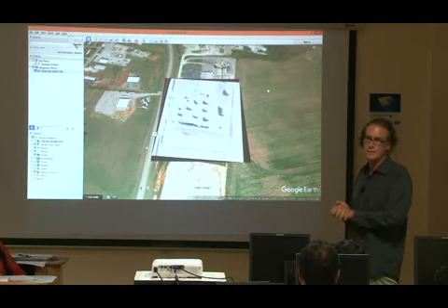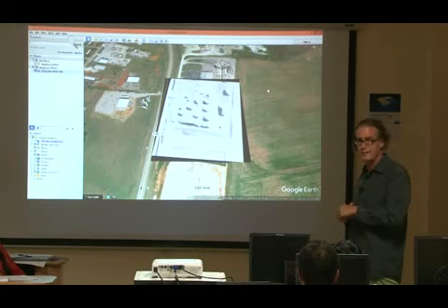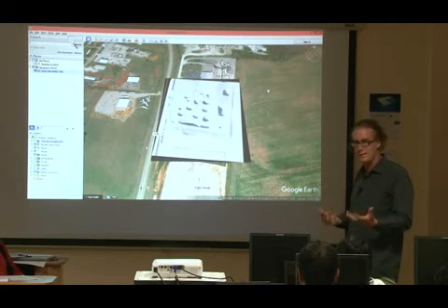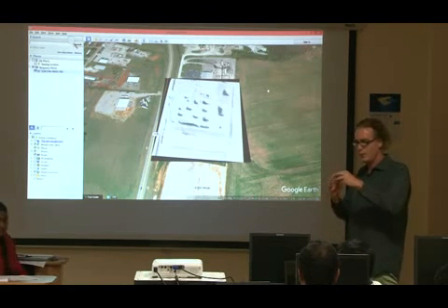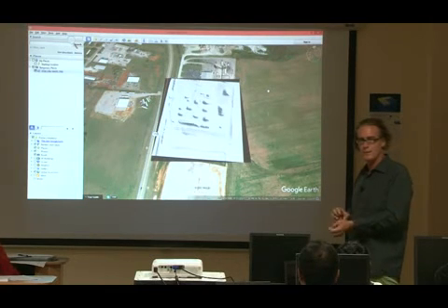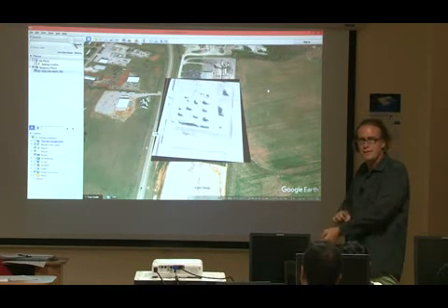The good thing is, with LiDAR, you do get affected by the smoke, because the smoke, just like a cloud, blocks your LiDAR, your intensities go down, your first returns are up in the smoke, but your geometry doesn't get affected too much.